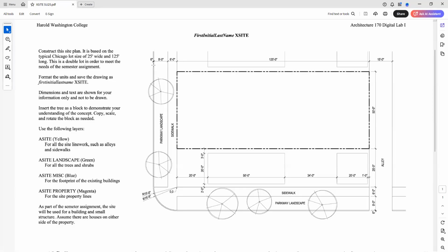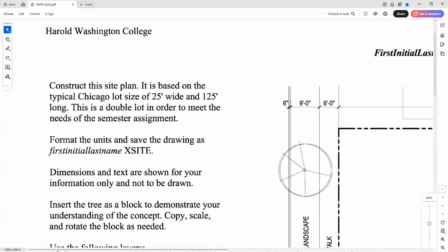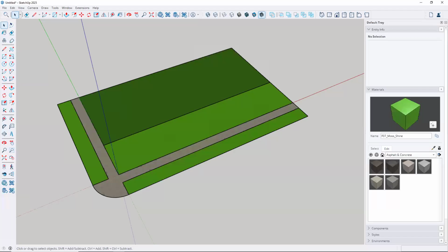curb over here. And this is where I'm going to start to introduce a bit of thickness. So let me move this out of the way. I just wanted to take a look, and it shows that the curb is 6 inches thick. And then the depth on it, because this is a 2D drawing, it doesn't show a depth. So we're just going to assume a depth of 6 inches as well. Or you can change it to 4 inches or 8 inches, whatever you'd like. Maybe take a look outside your house and see just how deep that curb is going to be.